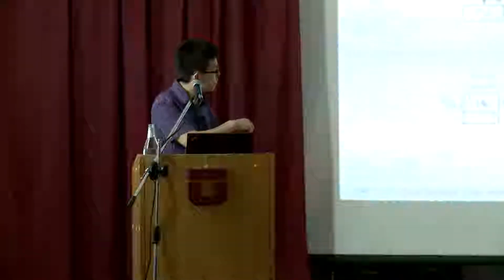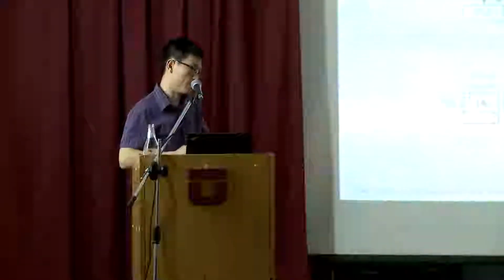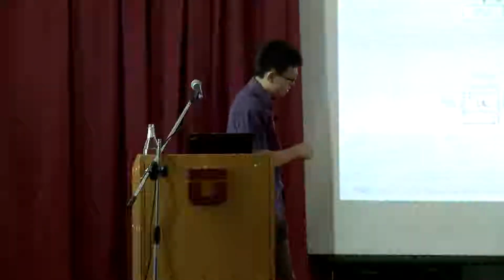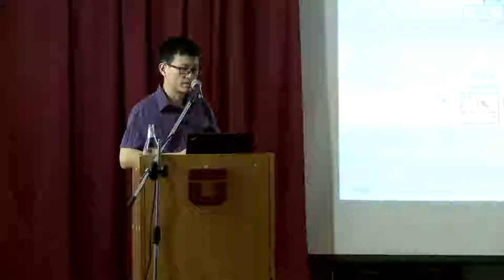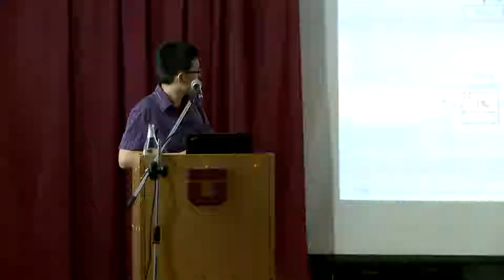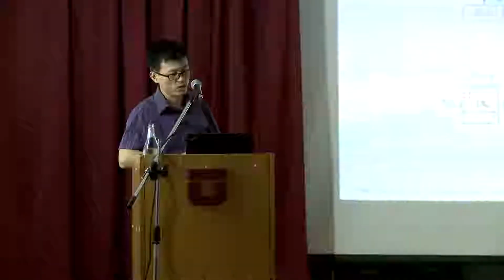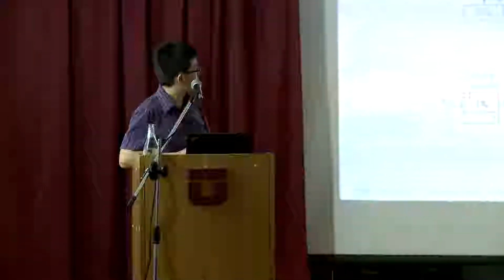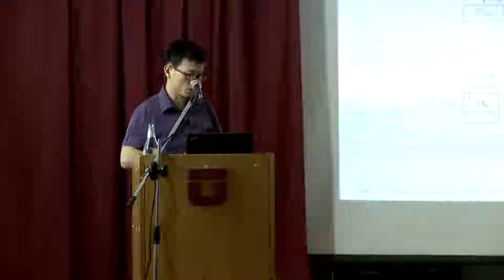So firstly, we look at standalone concepts. What's the impact of this droop on the standalone system? We can look at the current loop. For droop control, we said we have 2 different modes or types. One is current mode droop, which means I feed back the voltage to the droop block, and it gives me the IDC reference. This is called the current loop, current mode droop. All the others are the same, the only thing that is different is that you have VDC feedback to the droop block.